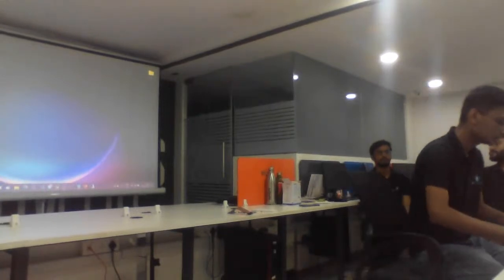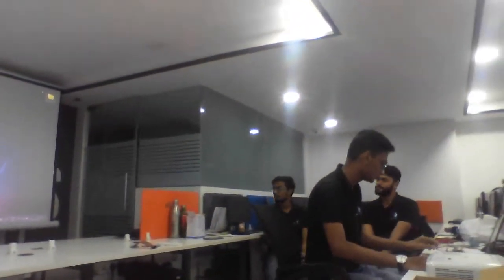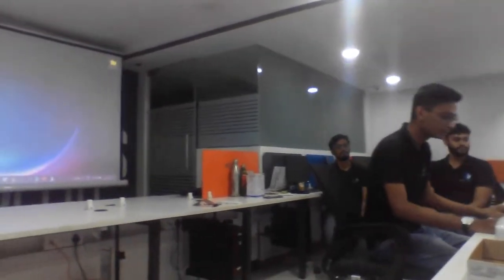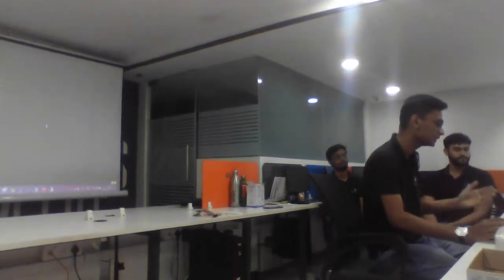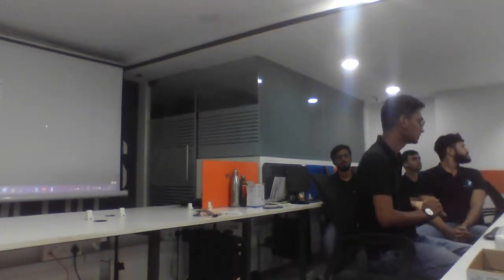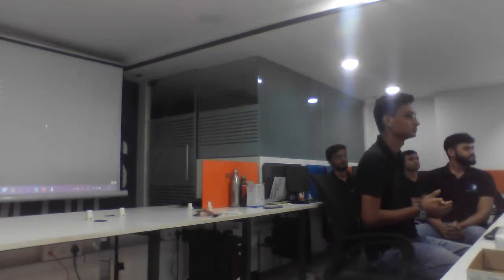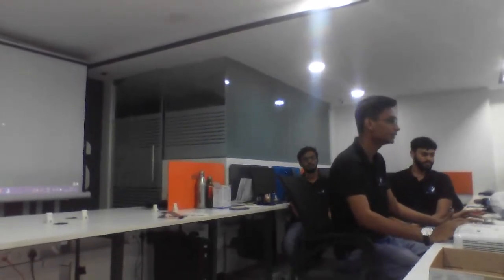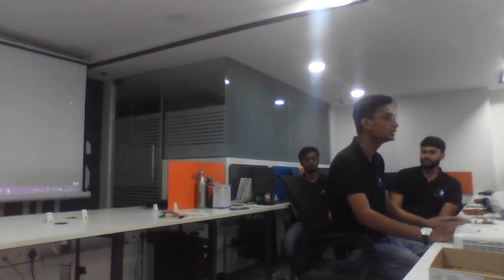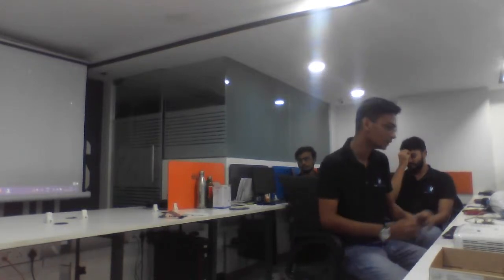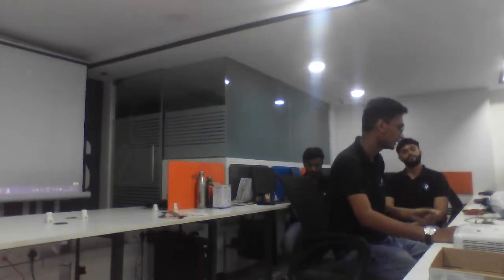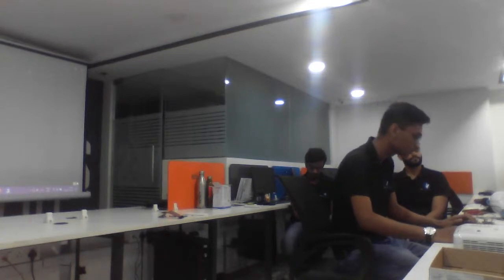So first, we will need a few hardware things. First thing is we will need an SD card reader. So does anyone know why? What is the main purpose of the SD card in our project, when we are using Raspberry Pi? Okay, yeah. So basically, Raspberry Pi is a mini CPU, right? So Raspberry Pi will need an OS to perform certain operations. So we can use an SD card and install an OS, and then it can be connected and be used. So for that, we will use a tool called Raspberry Pi Imager.